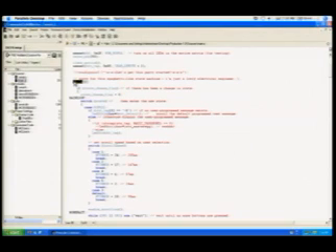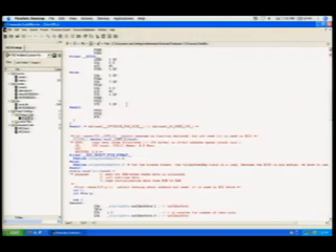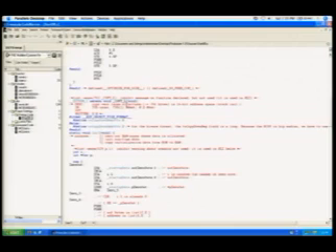Anyway, you'll notice that it says while 1. So basically, this will execute this loop of code forever. After it starts up, there's initialization code somewhere in here, which is, as you see, assembly code. It initializes various registers on this chip and gets it configured for working with these shifters on the back and the optional accelerometer and Zigbee chip, so that the chip knows how to talk to its peripherals. That all happens before you hit the main loop.